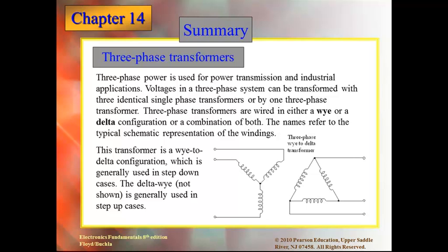We have a delta to Y transformer in the college here that goes from 480 volts that we use for some of our HVAC equipment down to 120/208 that we use for almost everything. We have 120 volts throughout the facility. And so that basically wraps up entry-level transformer talks. We're going to do some more with transformers and work on some labs so that we can hopefully get a better understanding of everything to do with transformers.